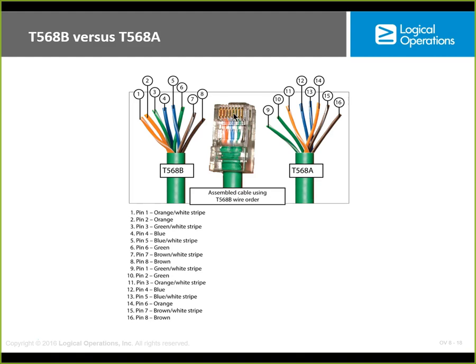The pins, the copper here, are actually little pins that penetrate the insulation. You don't strip the insulation off of these things. Little pins penetrate the insulation and make electrical contact. And then right here, which you probably can't really see, is a plastic piece that gets pushed down onto the case to hold the connector in place.